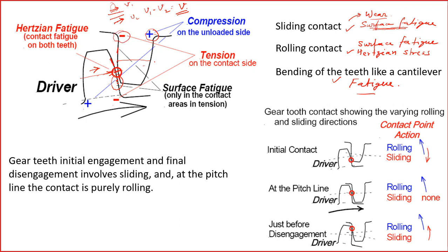Okay. So similarly, this will impose a reaction force on this one. So it will push in this direction. And because of this, there will be compression here and there will be tension here. So both teeth experience compression and tension at their bases, experience a huge amount of sliding, and experience a huge amount of Hertzian stress, which leads to fatigue. So these are the main causes why the gears will fail.